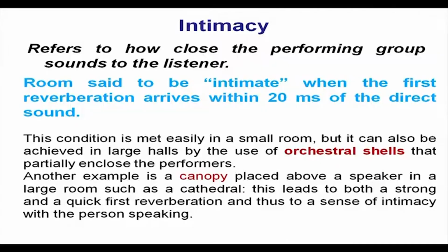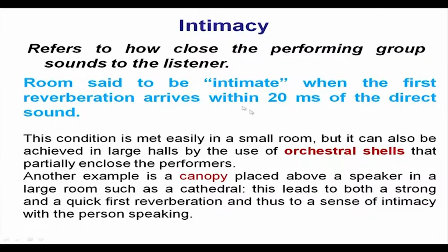So, intimacy refers to how close the performing group's sound is to the listeners. If a listener is sitting on a far seat, how does he feel that he is close to the orchestra? A room is said to be intimate when the first reflection arrives within 20 milliseconds of the direct sound.